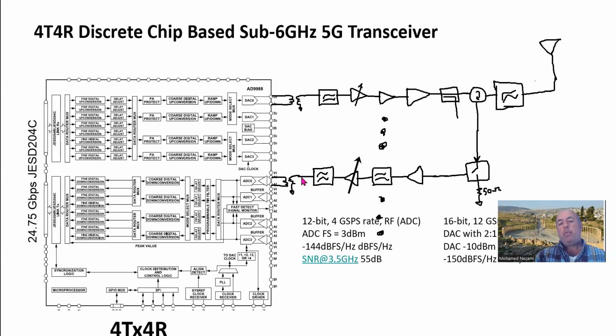So if you say operate at minus 30 dBm at this point, that means you know exactly how much gain you need overall in this path here. And it's usually on the order of 40 to 50 dB. So you're talking minus 60 dBm being picked up at this point here by the antenna, okay?